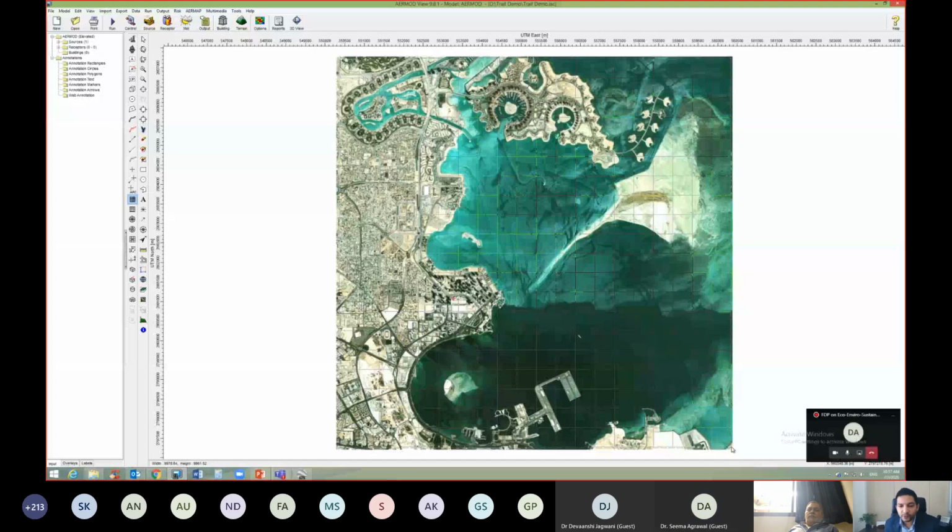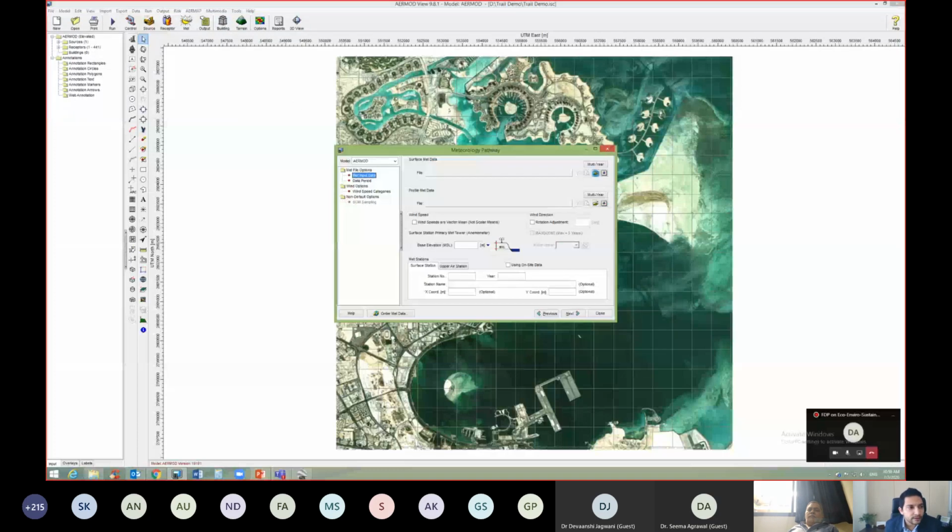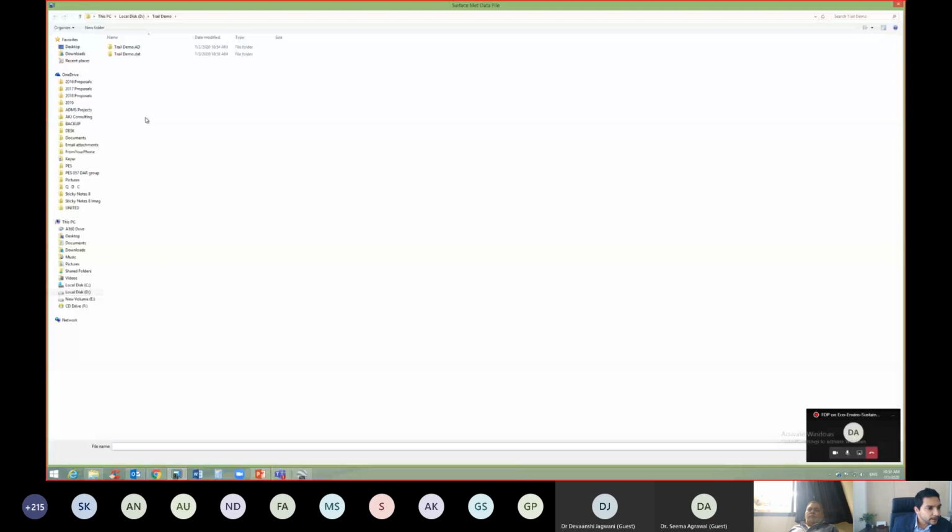I'm not generating a very dense receptor grid, because a dense receptor grid would take a long time. So now when we see the grid here, we would be able to get an emission value in each of the grid boxes. Now I'll just process this. Then if there's any building nearby, we can specify the buildings in this area. We'll go to the meteorological files. I'll just take one of the meteorological data sets.